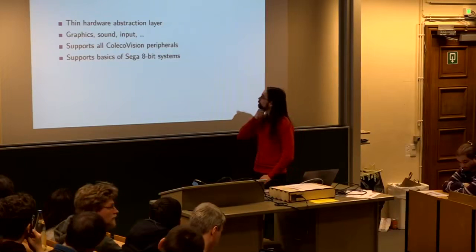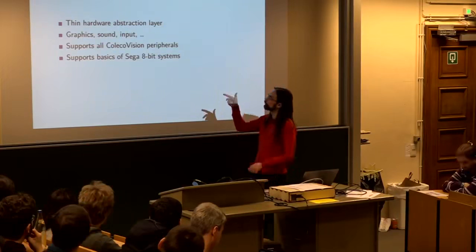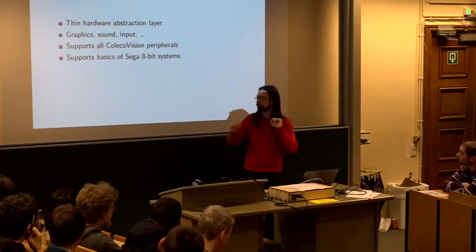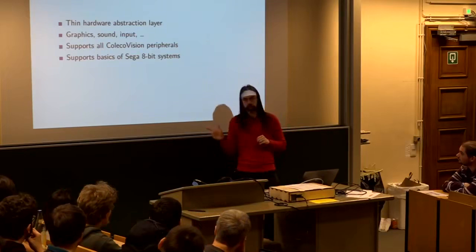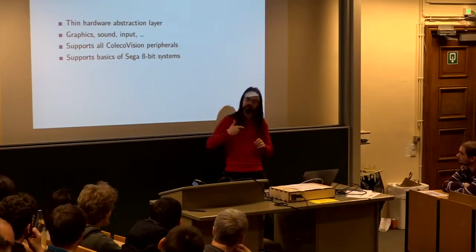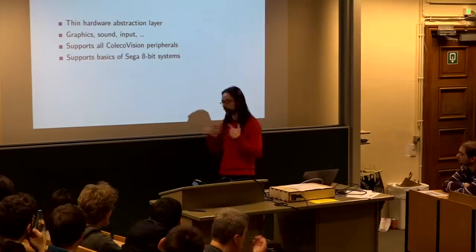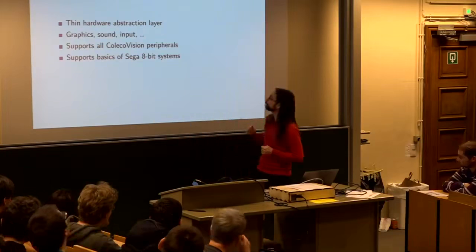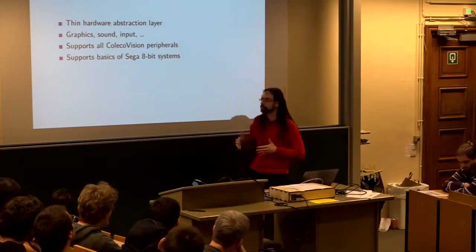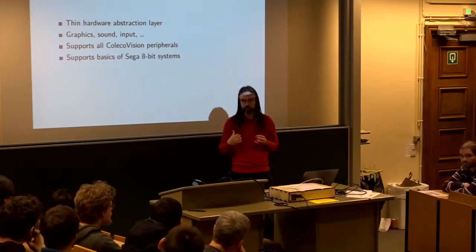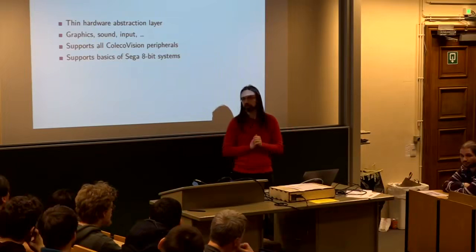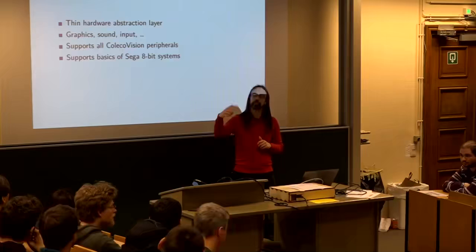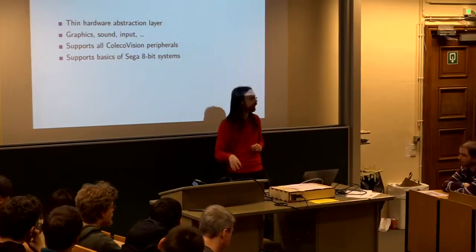And in particular, this is very nice because with just a change of the preprocessor define, you can compile a game written for the ColecoVision for the SG-1000 and it works. Of course, if you also want to support the Master System and not just have your game work there, but use the additional features, then it gets more complicated. If you want to use graphics mode 4, that's only on the Master System but not the other devices. You'll have to write separate code for that, but you can still make your game so that if you plug it into an SG-1000, it will work with the graphics capabilities there. If you plug it into a Mark III or Master System, it will use the advanced features.